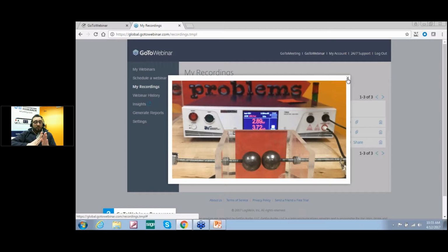They're spaced just closely enough to create an arcing condition, and as soon as the arc detection feature was enabled and the arc sensitivity level set to 5, which is the middle in that table we looked at, the arc detection circuit resulted in a failure. It caught an arcing event, and that's what the arc detection feature does: it catches any arcing event.